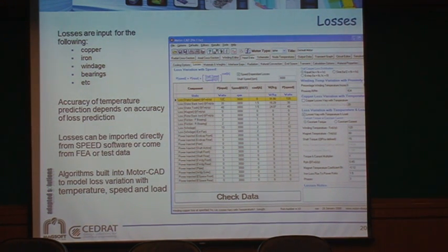You have something different, you have a machine. Maybe, for example, there is a parameter which is important: the interface gap. When you do your stator and you put it inside the housing, depending on your manufacturing quality, they may be stuck together, the stator back iron and the housing, or they may have some ridges. So you can adjust this, but once you know how your machines are made, there is no problem.